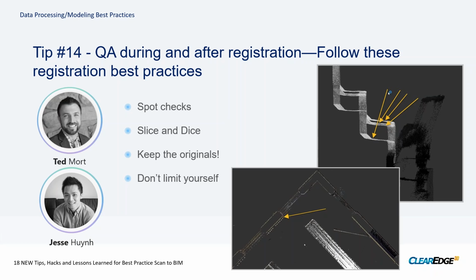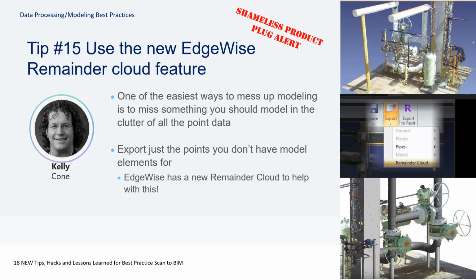We see this a fair amount with our software, because sometimes people will call us and they don't understand why our software can't extract a pipe or a duct, and we get the scan data and there's 3 pipes and they're all slightly overlapping, and we can extract 3 pipes, but we're not just getting 1. So registration's definitely important.